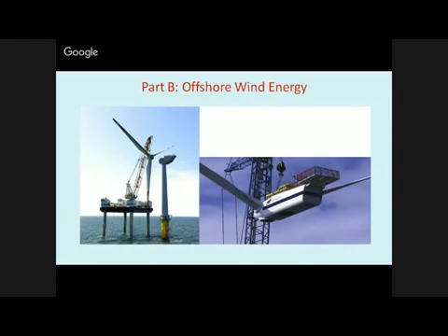sea also flows. So due to that reason, what happens? The velocity which you are getting on the sea is much, much higher as compared to on the land, because the land is stationary, and due to that force, the wind velocity reduces. So a wind turbine which gives 2 megawatt on land can give around 3 to 4 megawatt in the sea itself. You can say 50 to 100% higher power output, because the wind velocity is high due to less drag.